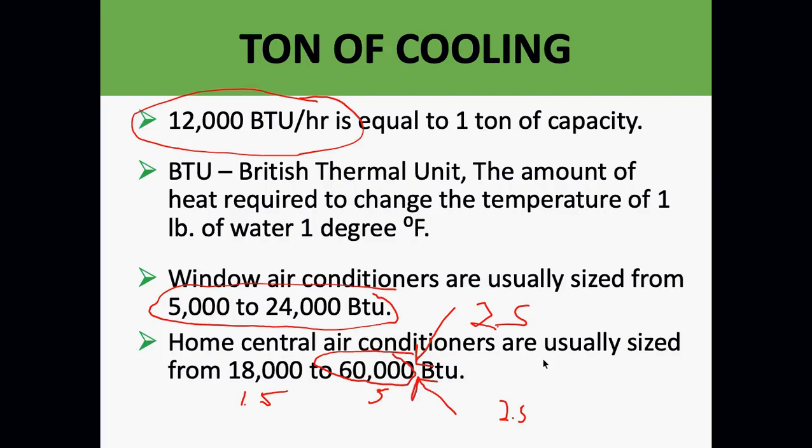If you do something like what we were talking about, one in the basement for the first floor, one in the attic for the second floor, it greatly reduces the ductwork as well. Yeah, and duct loss is a big issue. So, and the size of the ductwork, the cost of the ductwork.